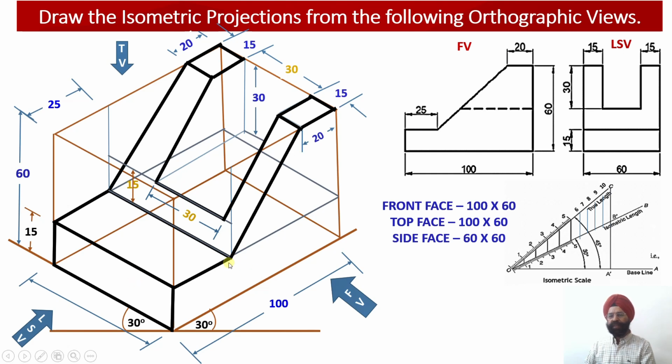So element number 1 has been drawn, and you can check there is no straight line over here. Since there is no straight line, it means this portion of the solid is connected to each other. So element 1 and element 2 from this front view are connected with each other. So this line will not be drawn dark. Rather, we have to draw this edge dark over here, and this edge should be drawn dark, so that we get a complete portion over here as a single unit. So this portion will be shown as a single unit, just like this way.